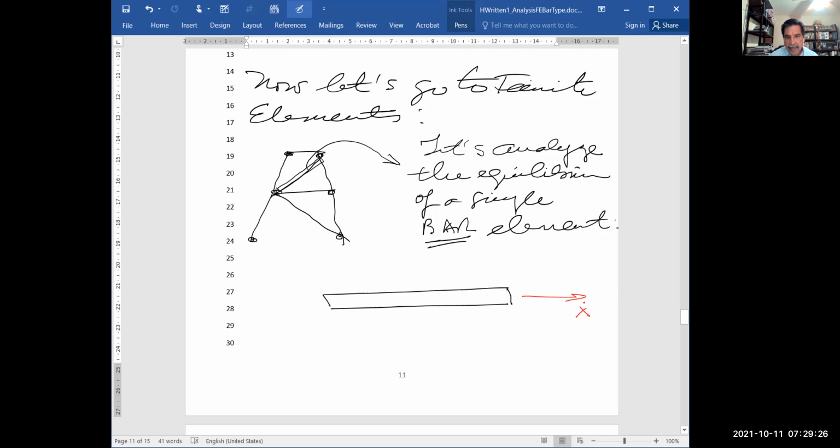That's why we use this hat, because this is local. In the same sense, in the vertical direction, this is what we call the local reference system. You can imagine that each one of these elements will have a different local reference system. It is true, so we have to set up something in order to set the equilibrium of the whole structure, but be patient.